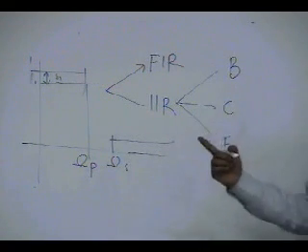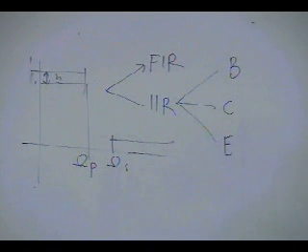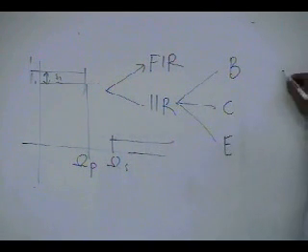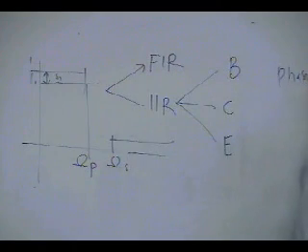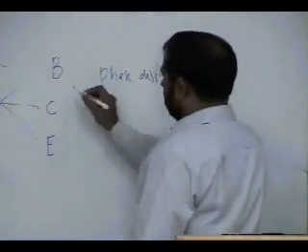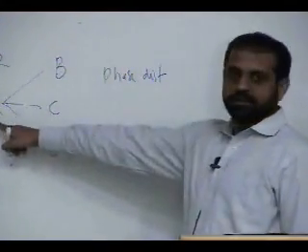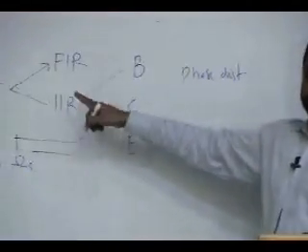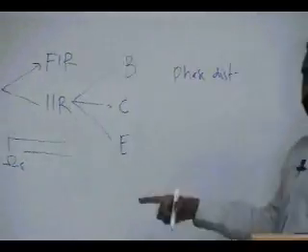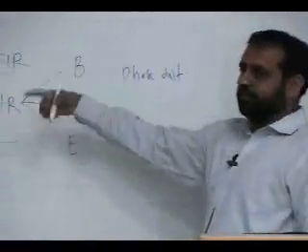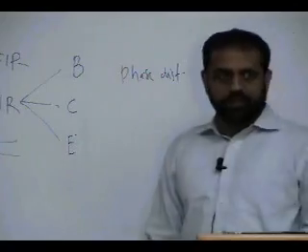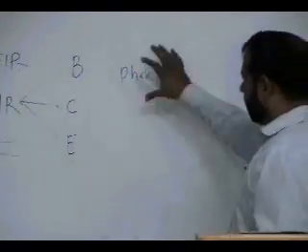What a bilinear transformation does is corrupt your phase. So if you use this, there will be phase distortion. The good thing is that a stable and causal filter in the S domain will guarantee a stable and causal filter that will meet your specification. If you're not too worried about phase and group delay, you do that.